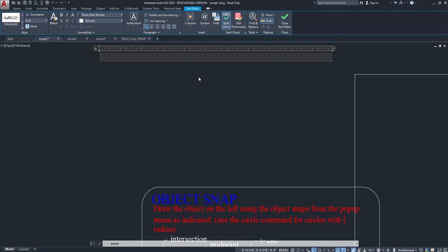So if I want to create a line that's 8 inches long, I just type 8 with an enter. Okay, 8, enter. And because the default unit in AutoCAD is the inch, AutoCAD will assume that that's 8 inches. If I want to do 8 feet, I have to type 8 and then the foot mark, and then enter.